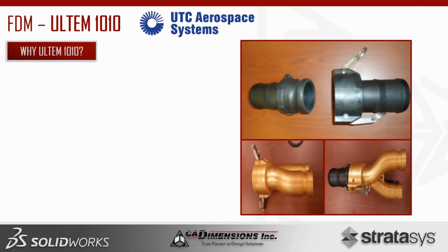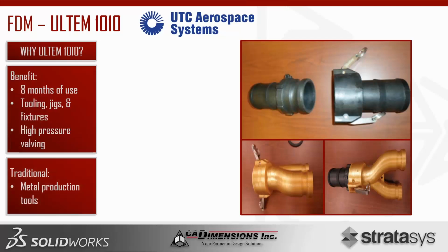And instead of having that designed again by an engineer and machined in metal, they were able to replicate this with ULTEM 1010 plastic. And the benefits were 8 months of life out of those parts, and the high repeatability of 3D printing, so if it broke, you're just able to print out another one, again, significantly cheaper and faster than getting it milled or machined. Tooling jigs and fixtures for the rest of their facility once they realized how versatile the technology is. And then, again, this is high pressure valving we're talking about, so several hundred PSI constantly going through at any given rate.